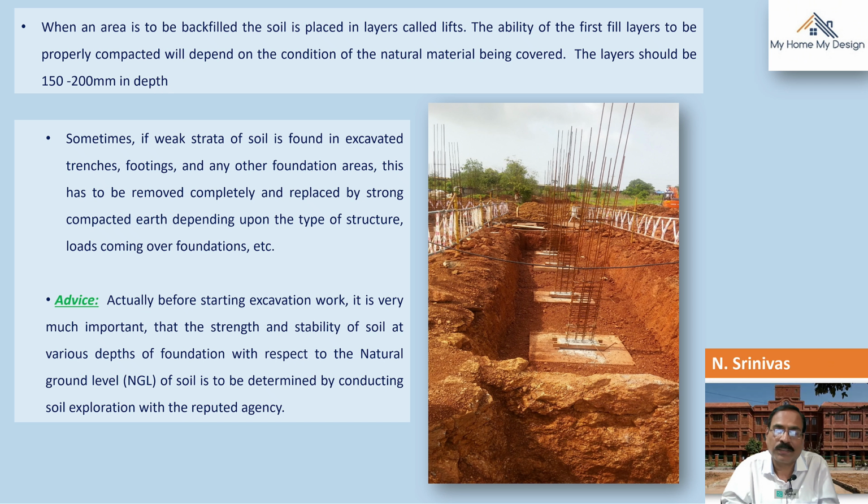That means soil test in practical terms. Call the agency, a reputed agency. They will conduct the test. 3-4 samples they will take out from the site, and with the help of those samples they will conduct the field dry density test in the laboratory, which gives 95% moisture content and proctor density, which gives a very good strength and stability result for the soil. Those tests, if they give more than 95% proctor density, are advisable for the backfilling purpose. Obtain the test results from the field laboratory.